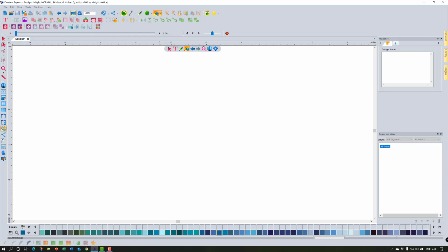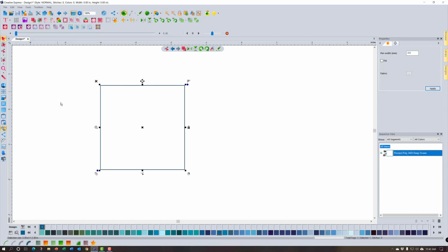So what I'm going to do is I've come up here to my built-in artwork shapes and I've grabbed a square, and you can see I'm in square because my cursor has a little rectangle by it, and I'm going to draw a square. Now to get a perfect square, if you remember from last month, you hold down the control key while you click and drag, and that confines the shape to a perfect square. When I let off, it creates that perfect square. I'm going to switch back to select mode to select it, and I need to make two shapes because what we're going to cover today only works when there are multiple shapes on the screen, and typically also when they overlap a little bit or a lot.